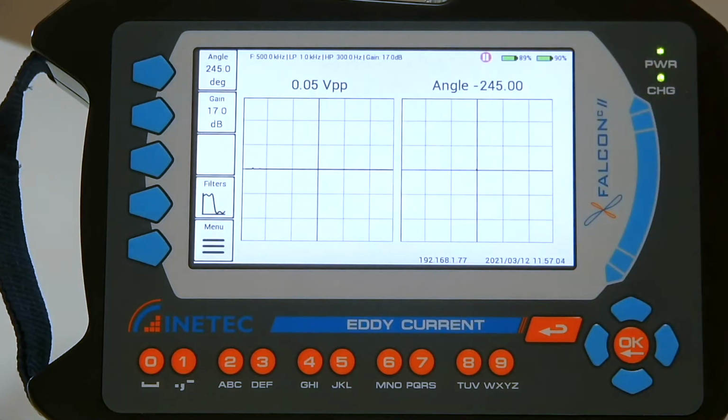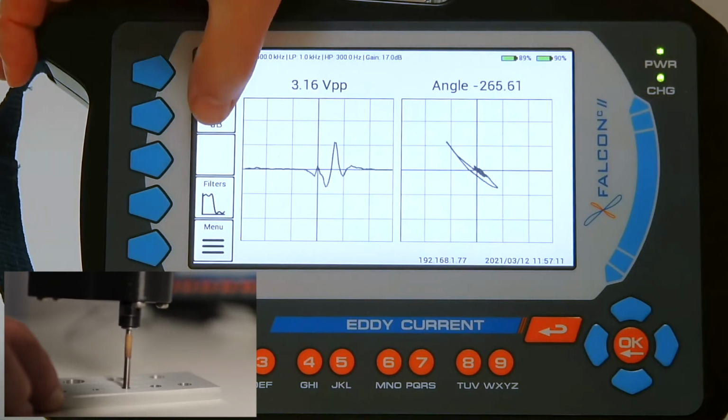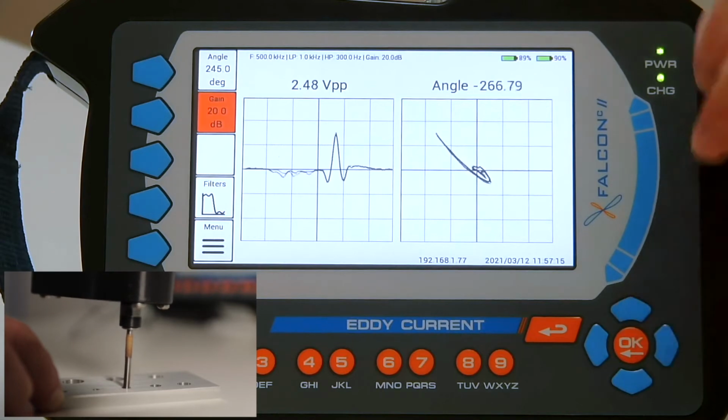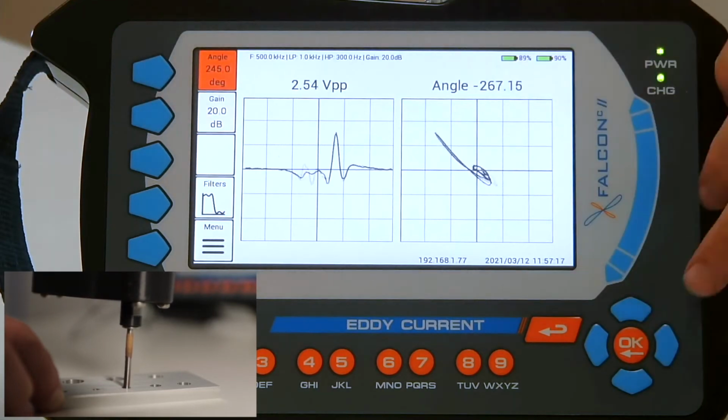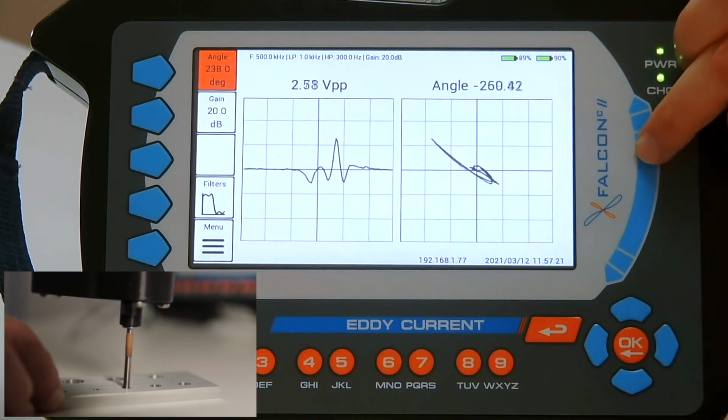Inspection of holes with rotating probe is of particular interest in aircraft maintenance. It usually takes place when skin repair is necessary with the use of a large number of rivets or primary structure in aluminium material, but also in steel when inspecting, for example, engine mount.